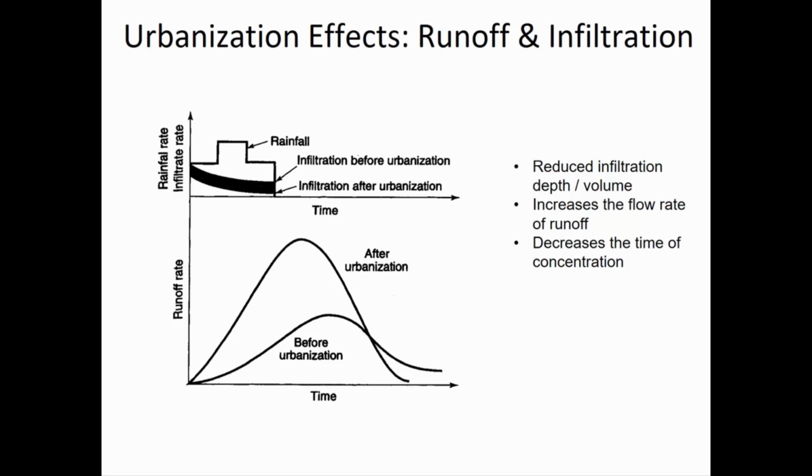The other half of that equation is that in addition to speeding up water, through urbanization you've also increased the amount of impermeable surfaces. A gravelly area or a vegetated field in the past would have a relatively low C value, which means a lot of water is infiltrating. But when you urbanize, the march is inevitably to put in roofs, asphalt for roadways, parking lots, and sidewalks or concrete, and none of that infiltrates water efficiently. So on the runoff hydrograph, the peak is sooner and higher.